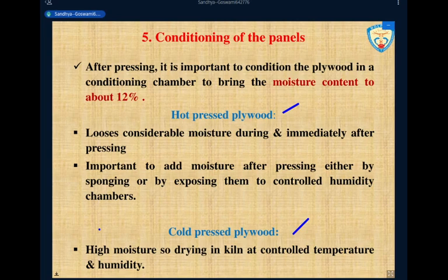If sponging is done, then they will also absorb moisture quickly because they are heated up at that time. So in hot pressed plywood, it is very important. It needs to be done immediately, otherwise the plywood's properties may get lost.